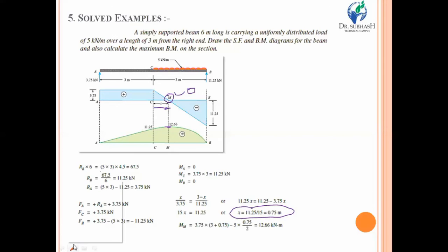So you just need to calculate the bending moment at section M, in a similar way to how we calculated the bending moment in all the other sections. Taking the left hand side, look at section M and the forces on its left, with the distances multiplied.